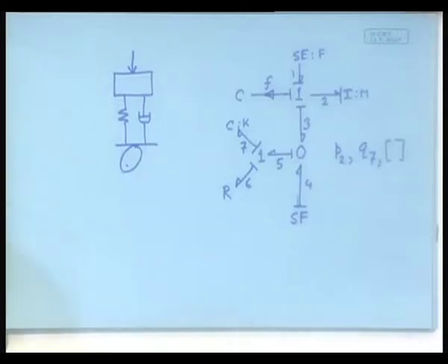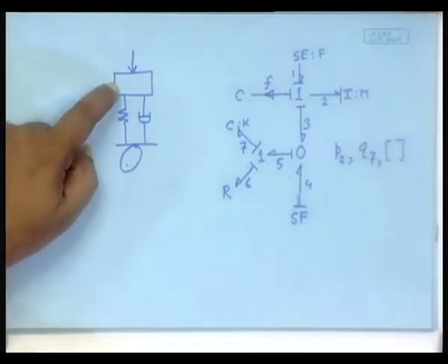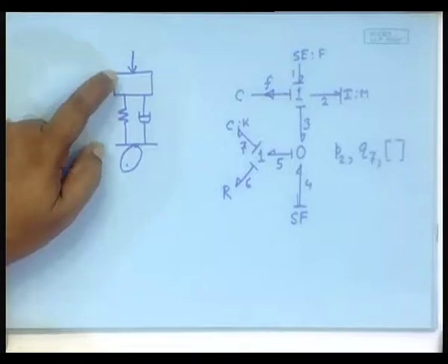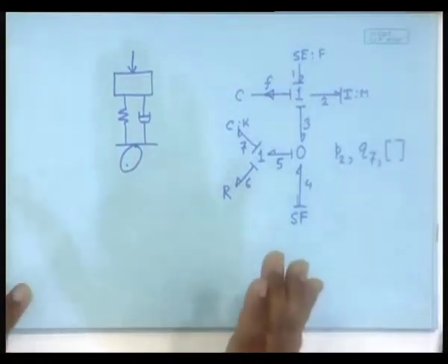Clear? So, why did we need it? Because we wanted to observe the position of this mass. So, in these situations we need to do that. A whole circuit in which there is a capacitor, you want to observe the current through that capacitor. What will you do? Current is proportional to the momentum. Therefore, you want to measure the current means somehow you have to get the momentum as a state variable, but momentum is not a state variable of a capacitor. What do you have to do? You have to connect a dummy inductor through an activated bond. The moment you do that, it will generate the necessary variable. Is the question clear now?